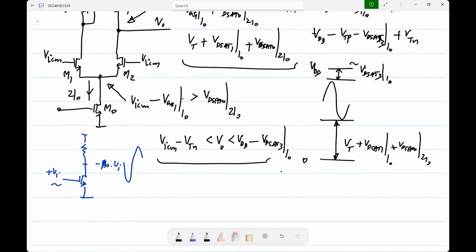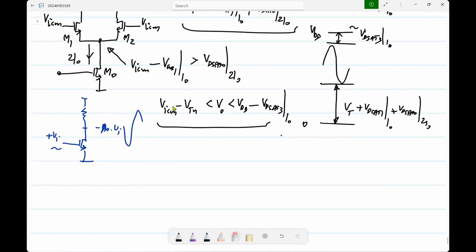We'll see the implications of this. We can do it for one particular case, and then after that, these things become automatic because we'll be reusing the same block, and you'll be able to evaluate them. This part I'm assuming you've already seen earlier, right? The swing limits of a differential pair. You should have seen that. If not, go back to your notes and check it out. So the output limits would be, again, you lose a lot less on the upper side.